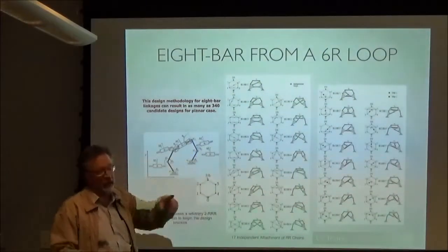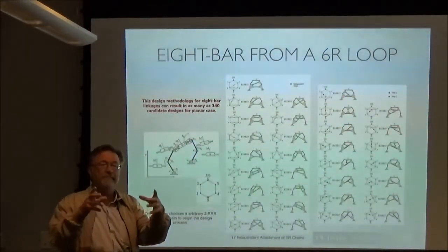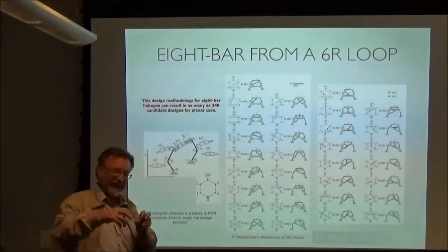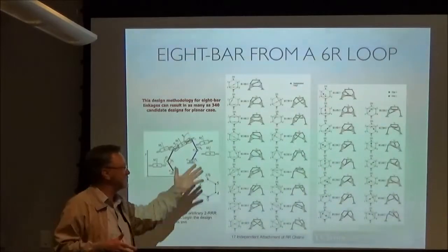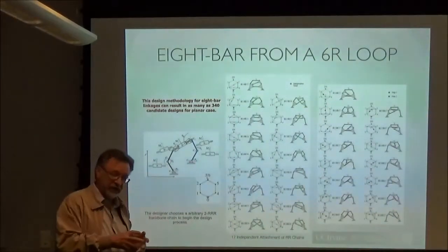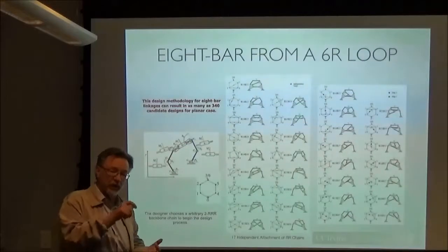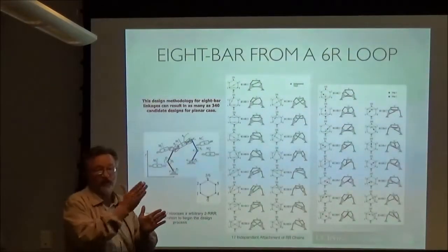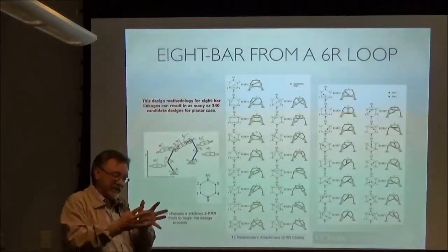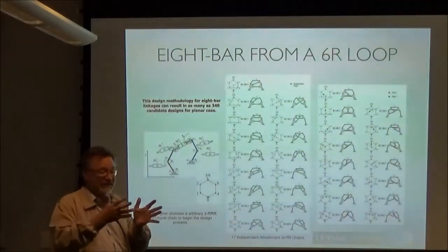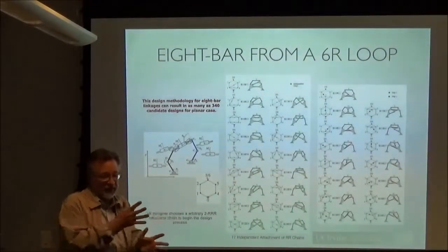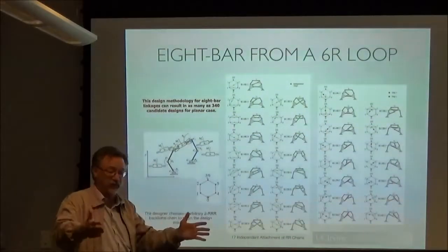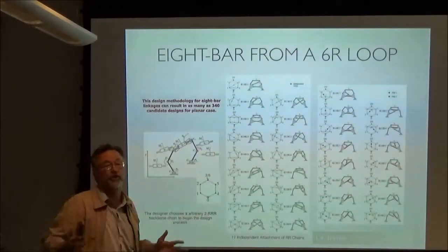And what you see here is planar loading with all the axles parallel. Most of the loading that damages these devices is out of plane. So you can't design these things the way they're drawn. You've got to seriously consider the out-of-plane structure: the web, the flanges, the bearing supports. And these things have to move over each other, so they are spread out even further in space. You've got to take that into account. How you package them relative to each other in the plane is very important, and whether you actually package them in parallel. You might actually run two of them in parallel.